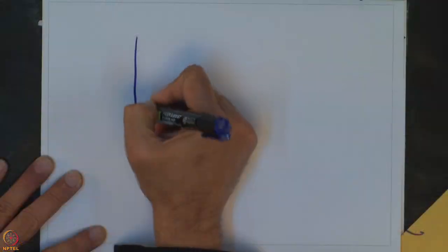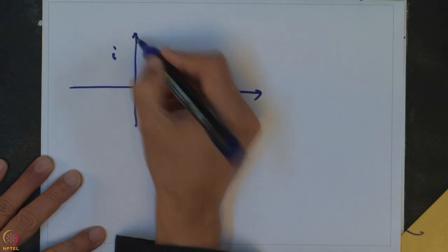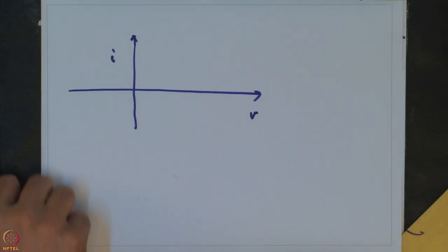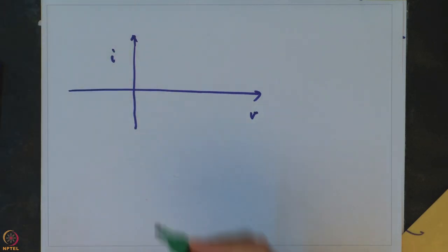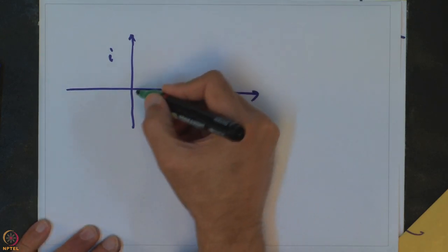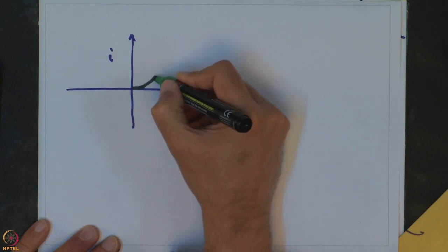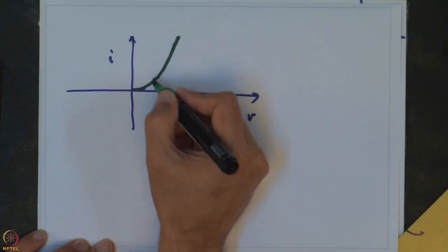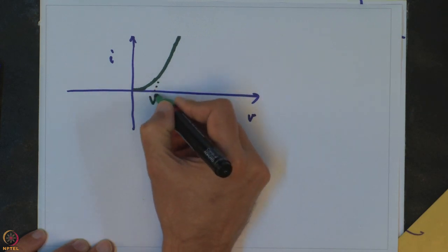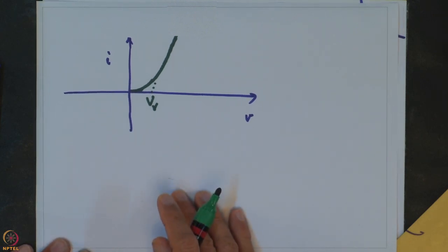One of them is in their IV characteristics. So, one of the things that you will see is that if I draw the IV characteristic of the 2 diodes, and let us say I use a green pen to draw the IV characteristic of a signal diode. You can see that it is going to rise exponentially later on, and there is what is called a cut-in potential or contact potential, and the device actually starts conducting only after that.